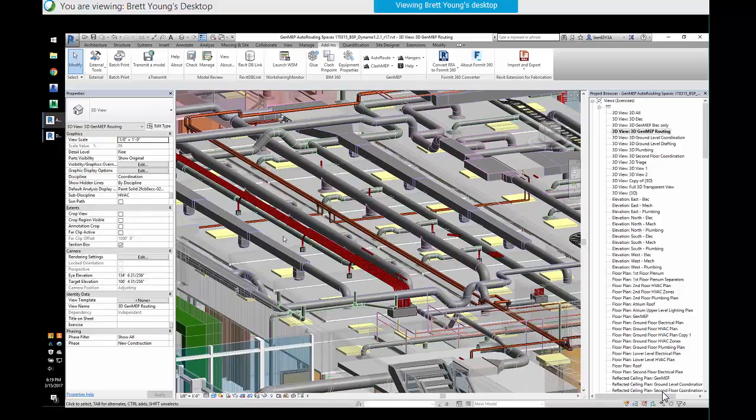And the question is, how do you get there from the electrical room? What elevation do you use to work your way across at a nice height so you can support all those conduits? And what we've built is the basic example of GenMEP, routing from point A to point B, getting around the obstructions as necessary to find a clash-free route between point A and point B. But building on top of that in Dynamo is running from point A to point B and then moving point B to a different location and running it again and then comparing it against the point A route. So comparing many routes against other routes and finding the best way to get from point A to point B-ish, scoring it and figuring out the best way to do it. Not just a way, a definable, benchmarkable best way to do it.